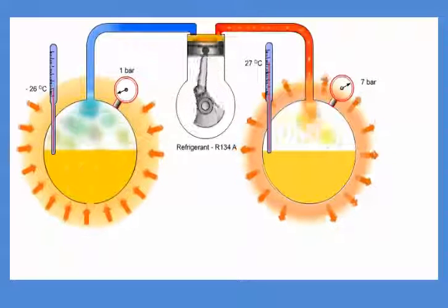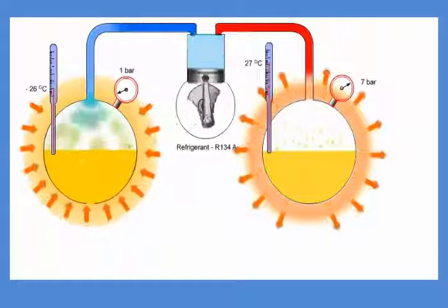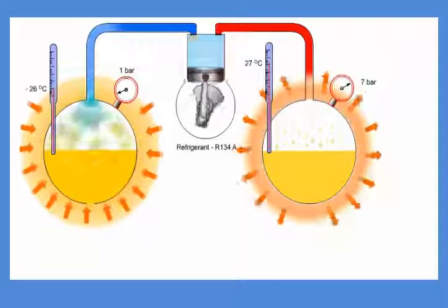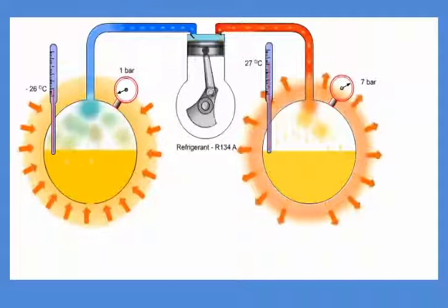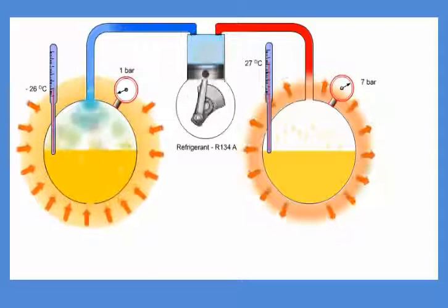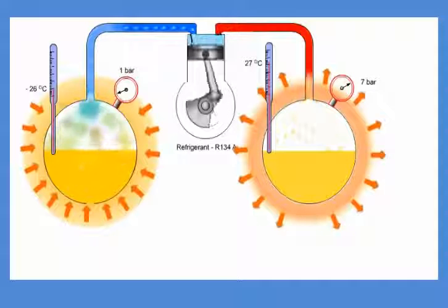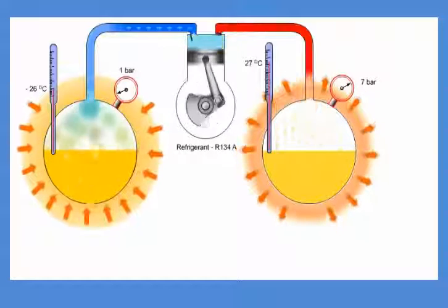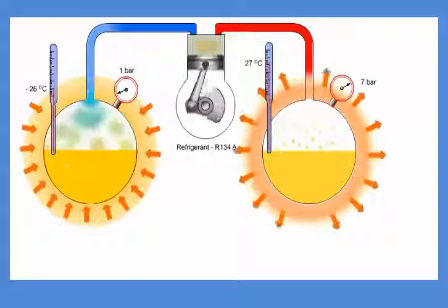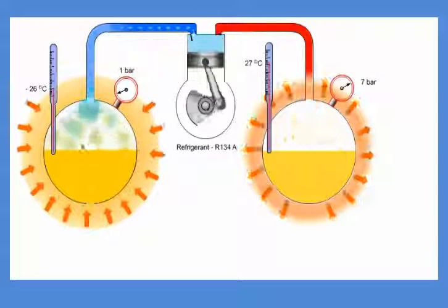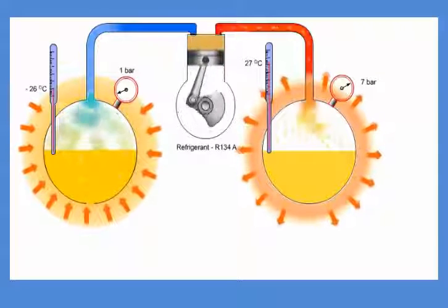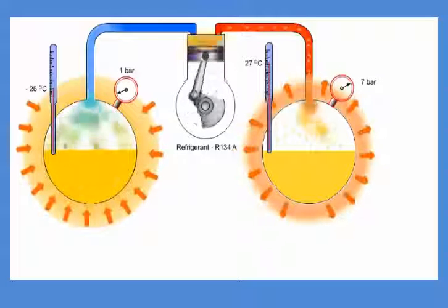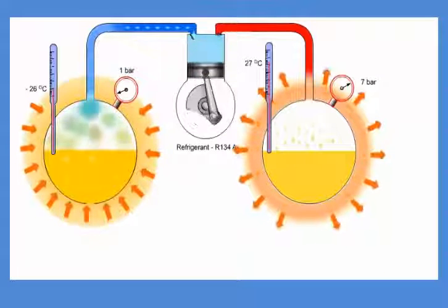In this flask, the refrigerant is cooled down and will start to condensate when it comes into the flask, because the refrigerant is exposed to the relatively cold surface of the flask, which is again exposed to the ambient temperature of 21 degrees Celsius on the outside of the flask. On the inside walls of this flask, you can see that liquid drops are formed and running down the walls to the surface of the liquid in the lower part of the flask.